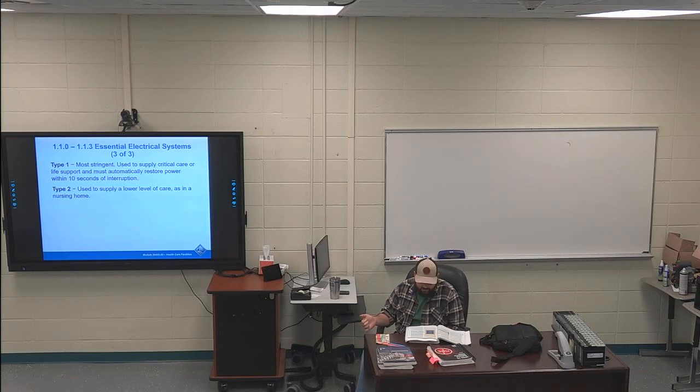Going on to page 5. The second paragraph in the top right of page 5, last sentence is highlighted. A single transfer switch. A transfer switch is what switches from normal power to emergency power. A single transfer switch will serve one or more branches of a system in a facility with a maximum demand on the type 2 EES of 150 kilovolt amps, as shown in NEC informational note figure 517.42B. So if you have a single switch, it can only supply up to 150 kilovolt amps.